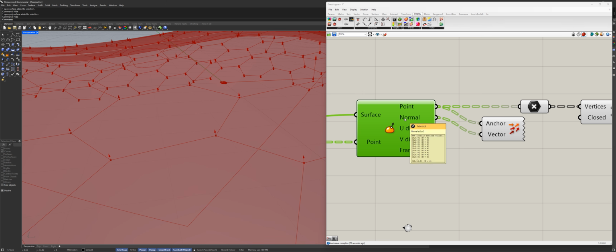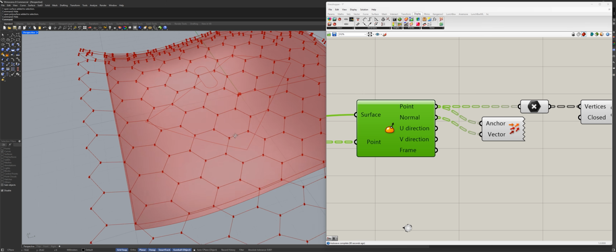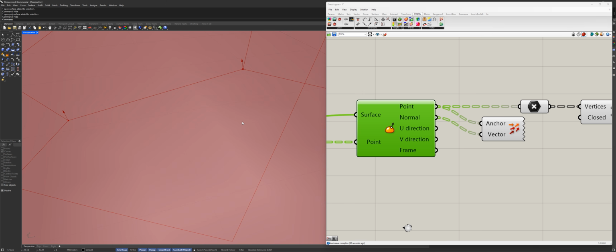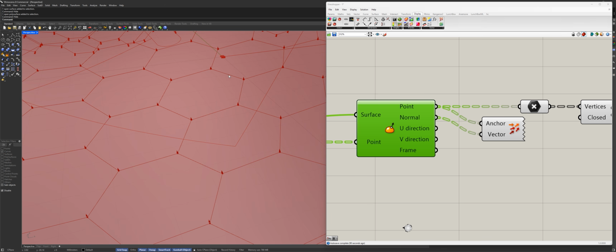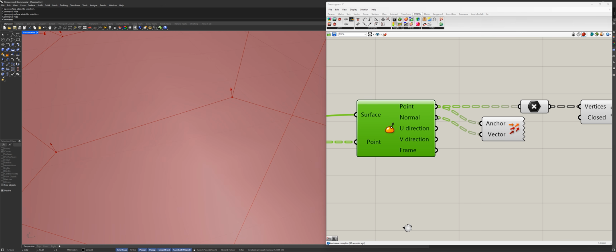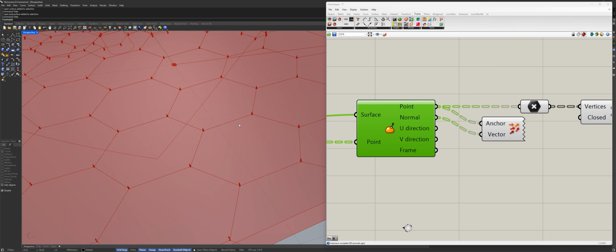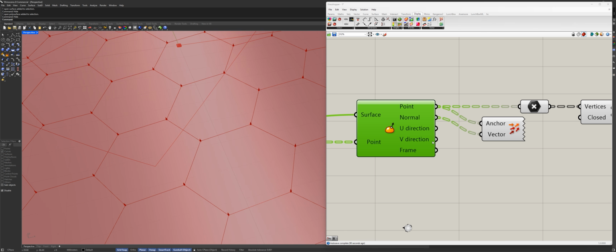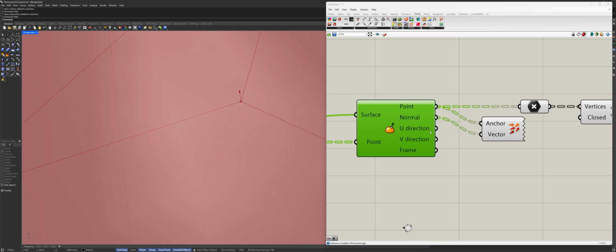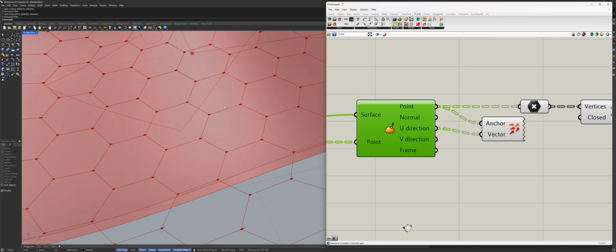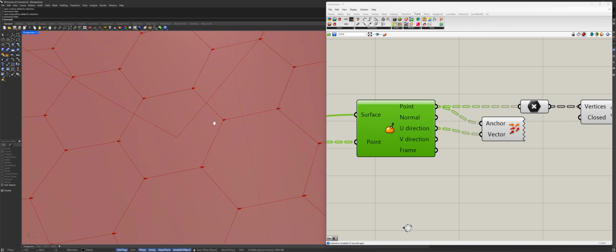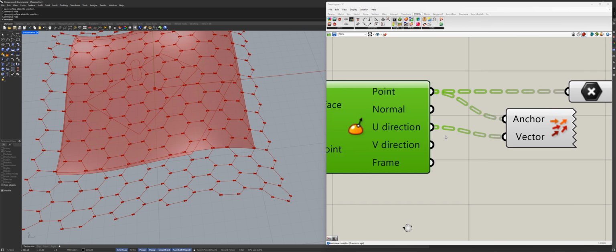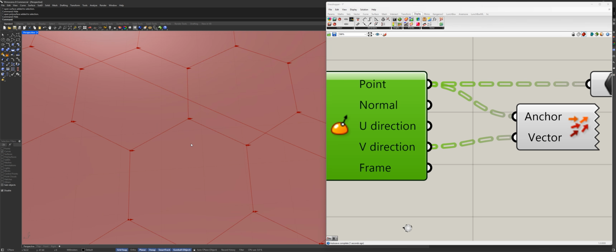And the normals just take the curvature vector, whatever amplitude it has, and unitize that, making its value 1. This is a very standard procedure, and not, by the way, only in NURBS geometry, but in polygonal modeling, even though the normals are calculated slightly differently. But the concept is the same, perpendicular vectors, right? Normals means unitized. The next two vectors are U direction and V direction. They are vectors also, and they are also unitized. So the U direction at every given point shows me the vector which follows the direction of the U domain, and the V direction the direction of the V domain.